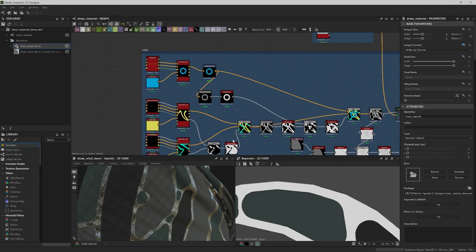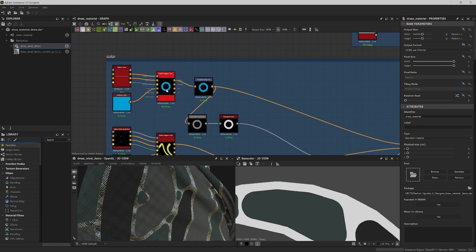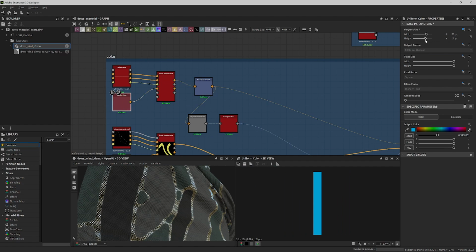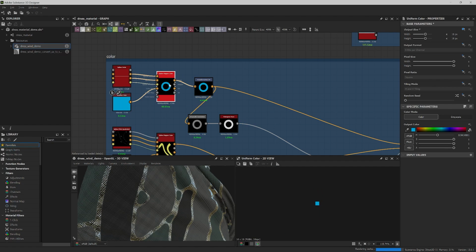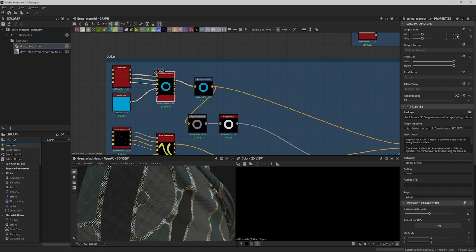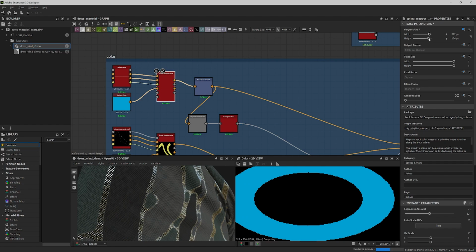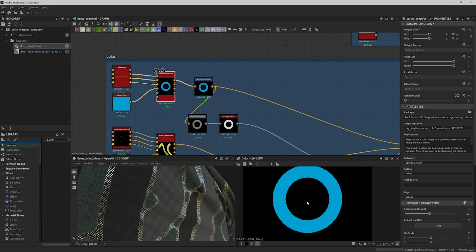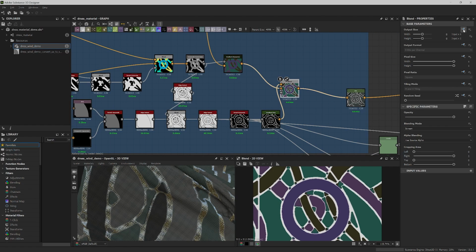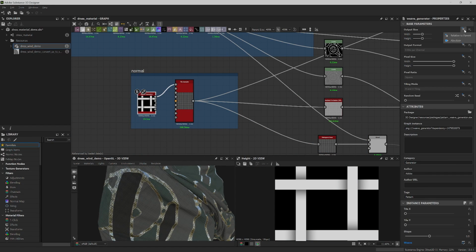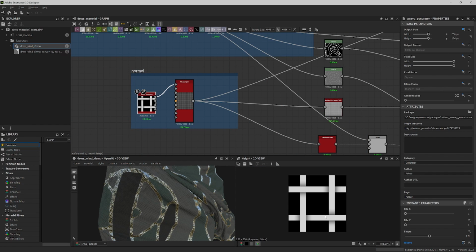Alright, we've now finished our graph and are ready to optimize it. For this, consider the balance between quality and processing footprint for each node. First off, change all uniform color nodes to absolute output size and their width and height to 16 pixels. Then change all your graphics to absolute and as low a width and height as possible without losing significant quality. If you see that the quality deteriorates too much and you get unwanted artifacts or mismatches, raise the resolution back up until they're resolved. Let's also make some adjustments to the weave generator node and the tile sampler.